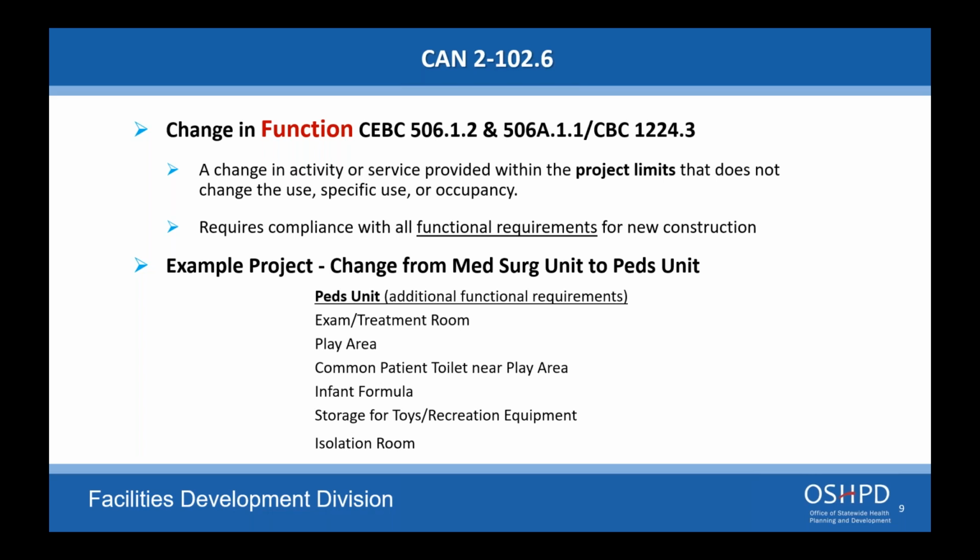It may. Again, you're remodeling, now you're remodeling the space. You're changing the toilet room, you're remodeling it. So it would probably need to be fully compliant. I don't see the question on the list, so I'm trying to go from what you're telling me. Oh, there it is. Yeah, if you're changing walls, it's a remodel. Again, you're defining the scope. Everything in that room now is considered new for an alteration. So that room needs to be compliant. Especially if you're changing walls, you're going beyond.